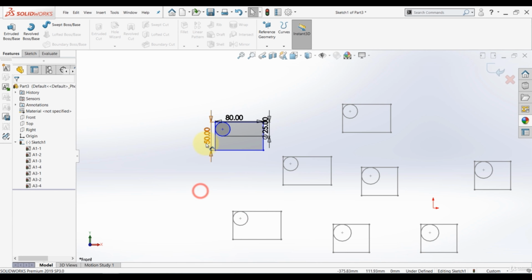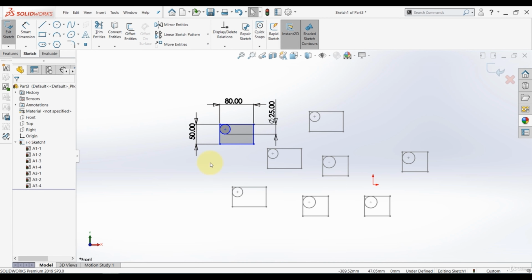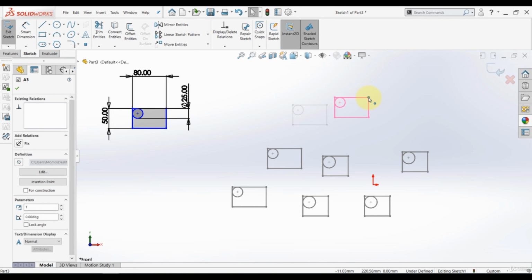Now, this is no longer one unit. You can deal with it as regular sketch entities. Dealing with the blocks makes it easier to deal with the sketch. Like imagine if you need to move this part. You will need to select Move Entities, or simply you need to define a lot of dimensions and relations so you can move it as one unit. And if you have any mistake, you will have a different shape. But in this case, you deal with this as one unit.